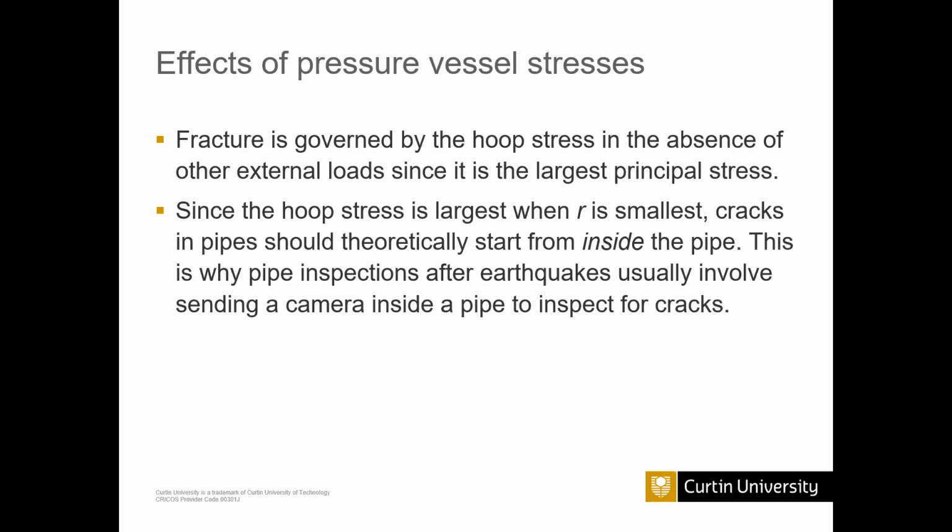If it exceeds the yield stress, definitely a crack will be initiated at the inner surface. No one can see the crack on the outer surface until it propagates, because the inner surface is at a high stress. If you wait until the crack appears, it will be huge damage.